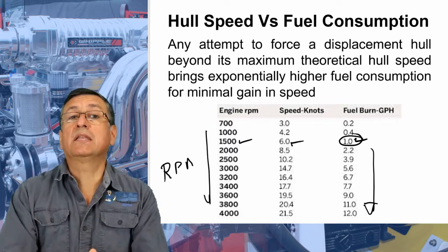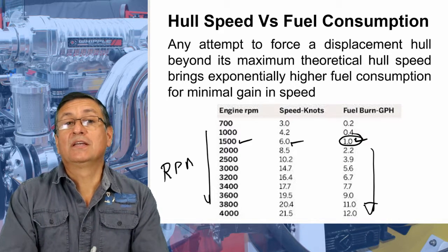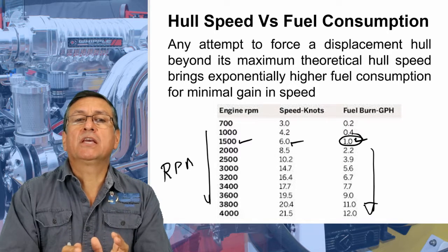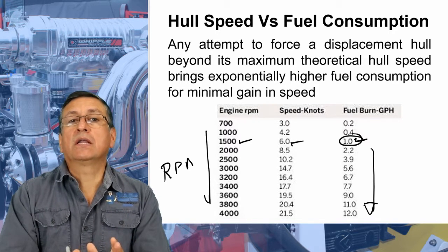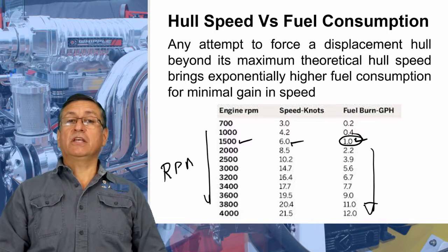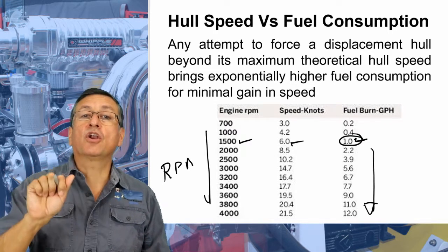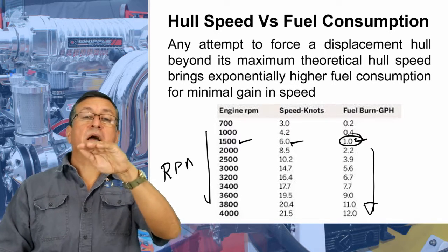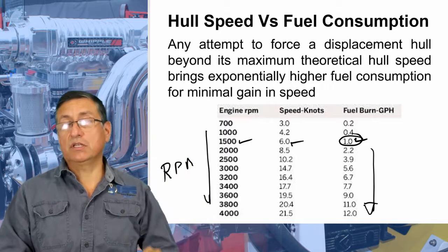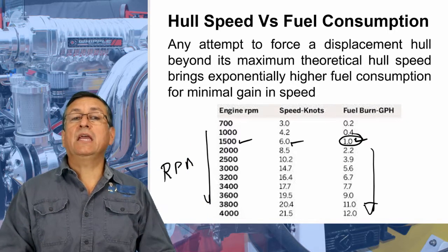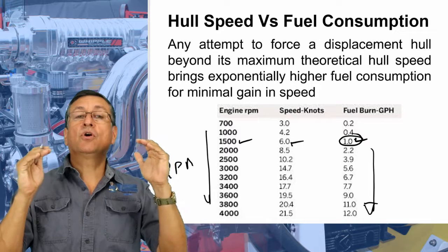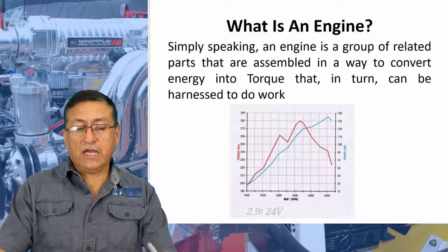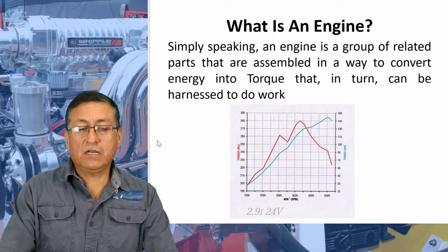Only to keep in mind when you operate your boat, try to use the boat always at the peak torque, at the point where, according to the manufacturer's recommendations, the engine should be running constantly. This is the point where the maximum efficiency is produced, and this is the point where the engine has less consumption, or optimal consumption of fuel. All right, don't forget, this is very important.